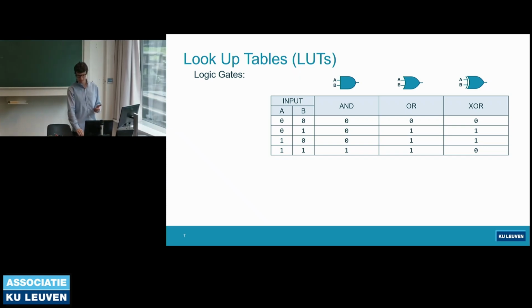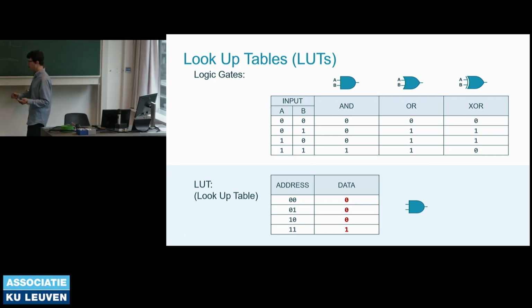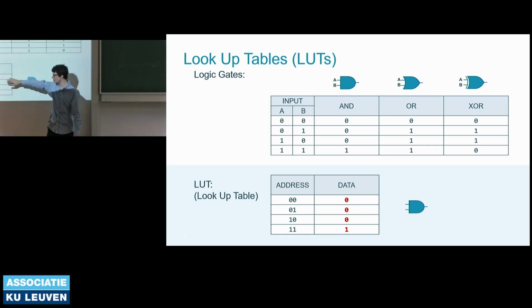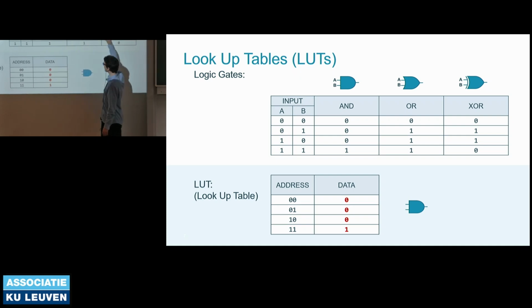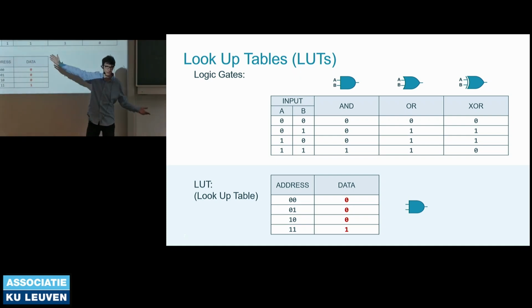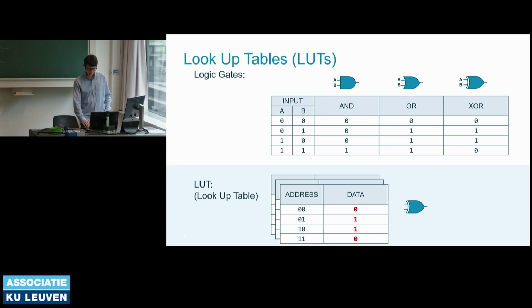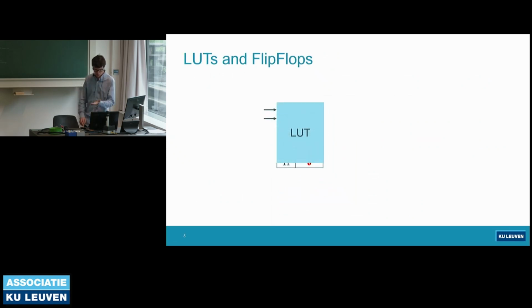Circuits that can be used to implement things like AND, OR, XOR gates, all your standard things. And these are implemented as lookup tables. So on the chip itself, once you have a lookup table on a chip like this, you can implement any of these, because a lookup table which takes 2 bits as input and 1 bit as output can implement any of these 3 things. You just have to program it to implement one of these 3 things. And so, to implement one of these 3 things, what we want is a lookup table.